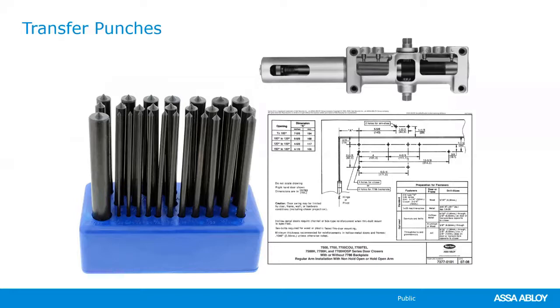If we look at this Norton 7500 door closer, for example, a really efficient way of installing this particular door closer is to get your first hole, your first mounting hole, which would be position A on the template.